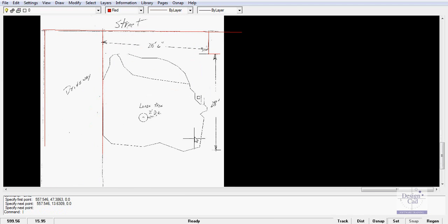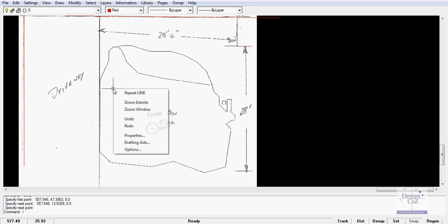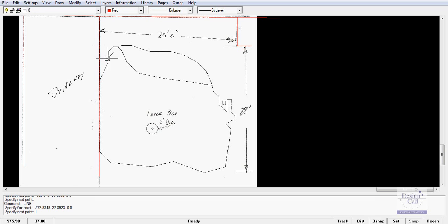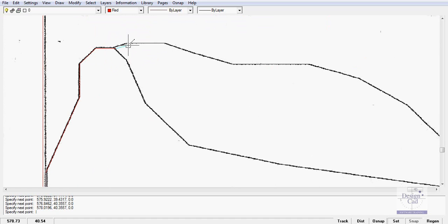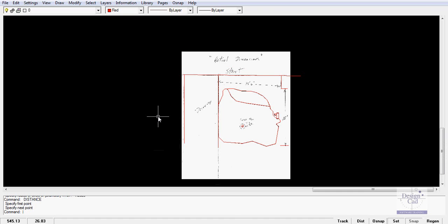Now, the garden bed, the edging of the garden bed, or this might in fact be an area of planting. We're not too sure, but what we can do is repeat the line, and it's just click to there, to there, to there, and there. Roll in when you need a little more accuracy. There. There's another very short segment to that point there, across to there, through to there, and so on. I won't bore you with the detail of watching all of this, but you simply move around tracing over elements in the mud map. Well, we now have a properly scaled base plan to work with.